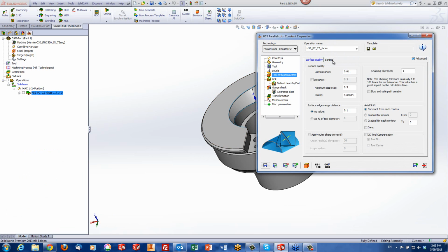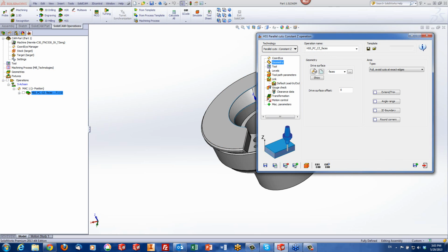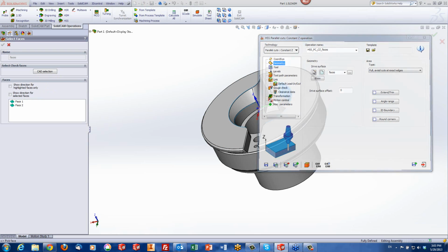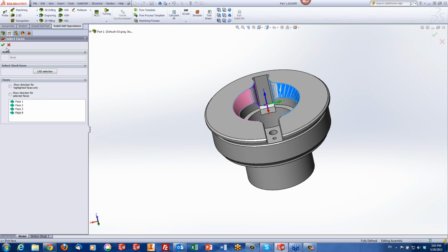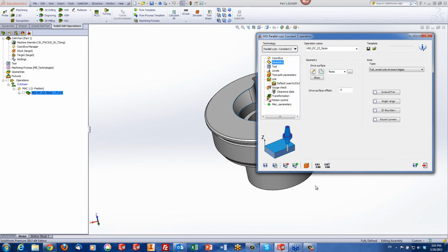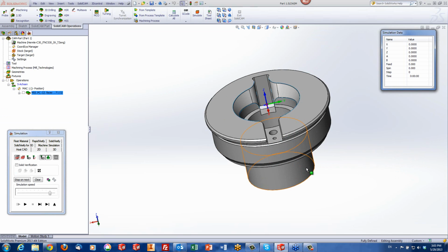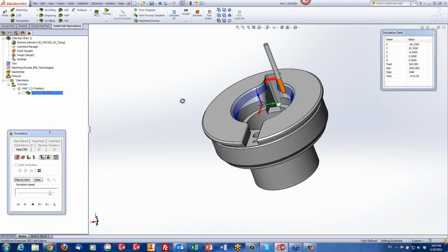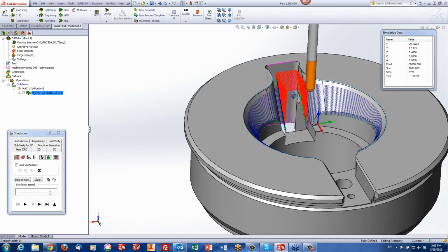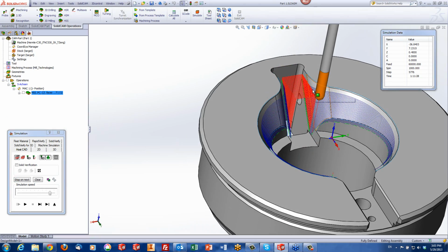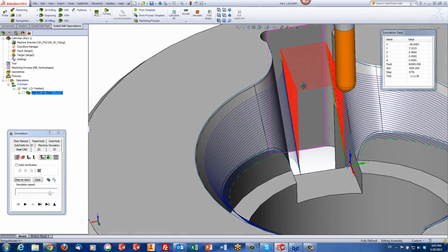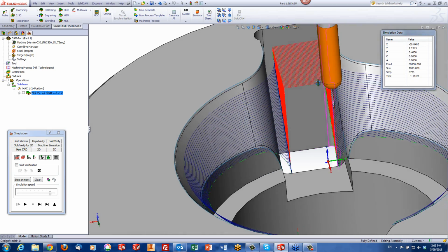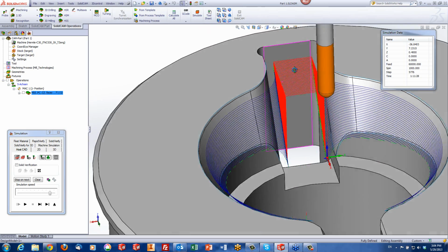So, rightfully thinking so, I would go to geometry and go to edit and just add those surfaces on over there, that one there as well. Just click on OK to accept, run my simulation, and we see that it machines both sides. However, note that now we have a gap between this surface and this surface, and it starts acting the way gaps act. If there's a large gap, in this particular case, it went up all the time.